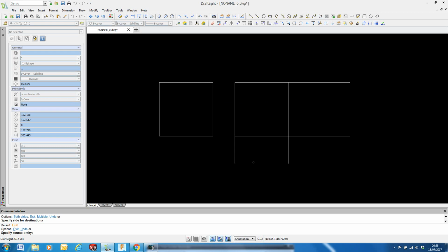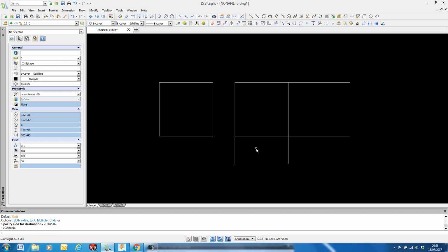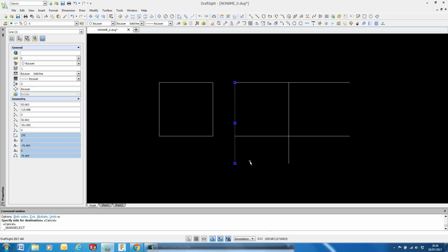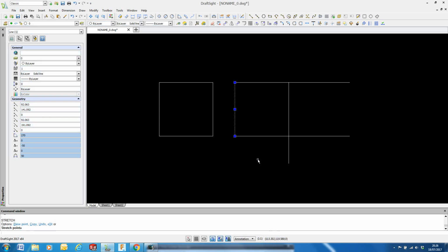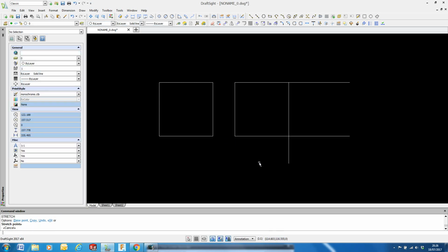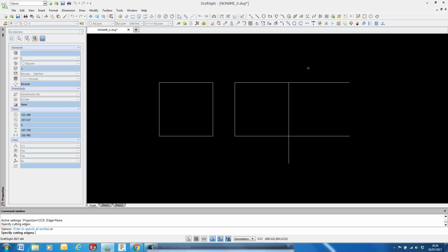but it's a bit untidy. A couple of things we could do there. We could manually press escape from the tool. We could manually select the line, grab the end point and reposition it. That works, no problem. Press the escape key to deselect that line. Or we can use the modify tool, trim, which is great.